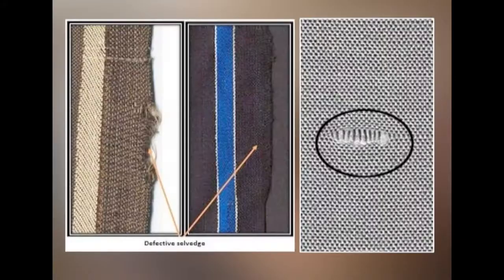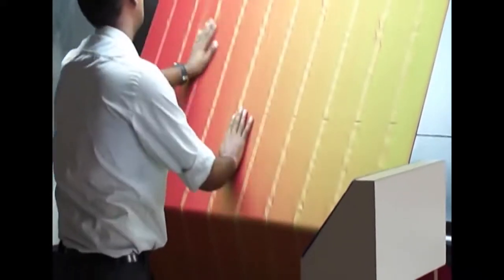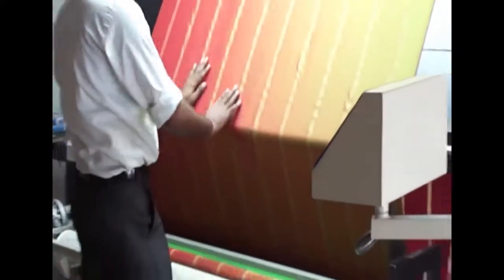It fails with big holes, torn selvages, etc., which are obvious. They cannot be corrected and the fabric must be cut and sold as seconds. Textile industries will flourish if the percent of seconds produced is low, as they lose the cost of fabric preparation and also the processing. So, quality checking at each and every stage of making fabrics is definitely necessary.